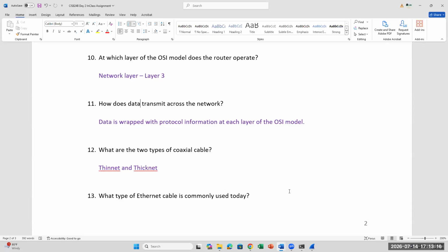Once you compress, you cannot use it again, right? So if the cable is too long, suppose it runs from the closet and all wraps around, and you cut it shorter, you just need to put the connector on the other end that you shortened and then compress it. This tool is about $10-15, and a bag of these is like $40-50, but you can get a bag of a few, and they come in blue, black, right?